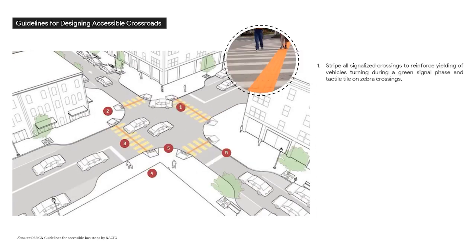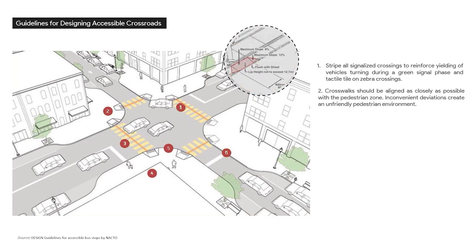Therefore, following the guidelines for designing crossroads: 1. All crossings should be well marked, with tactile tiles in the center provided as the guiding tool. 2. The crosswalks should be aligned as closely as possible with the pedestrian zone. Inconvenient deviations create an unfriendly pedestrian environment.